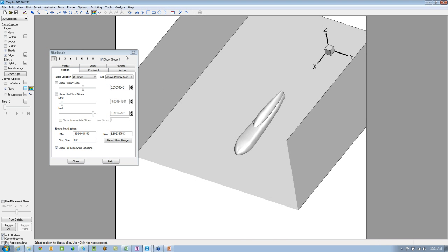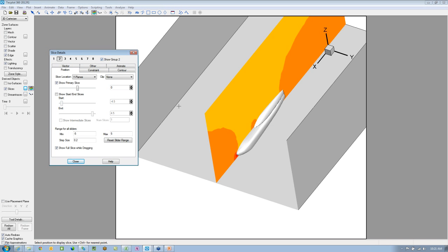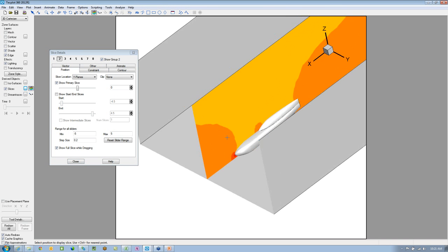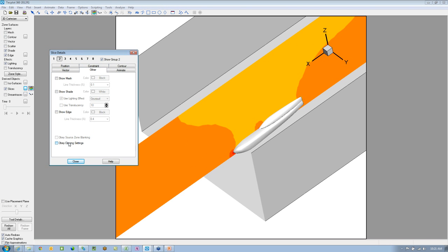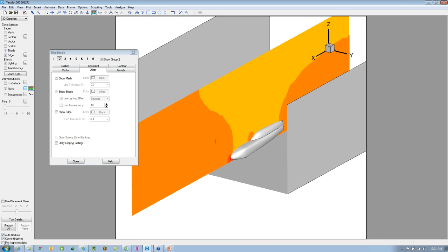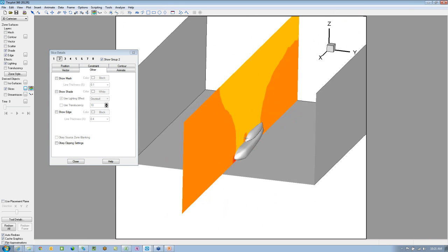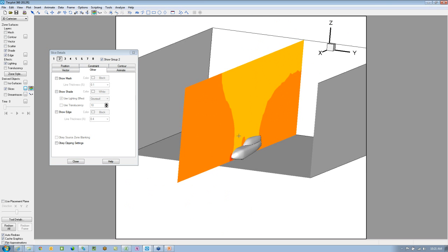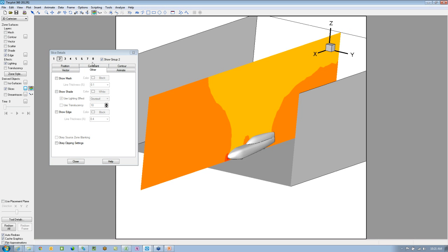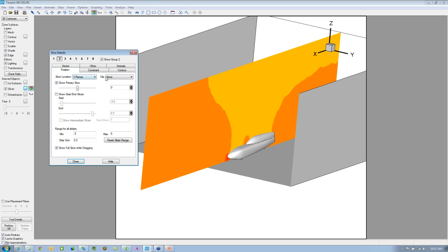Okay, and if I turn on a second slice group now, you notice that the slice group is actually following the clipping. But you do have the ability to say, well, you know, I don't want to obey clipping. I can turn that off. And in essence, you can start to clip off pieces of the geometry while still looking at slicing in other directions. And that's something we added about a release and a half ago, sorry, 2 releases ago. And a lot of people just aren't aware that that technology is available. And you can have up to 8 constraints, in this case, we're talking about clipping modes. So you can really kind of dice or slice and dice volume pretty well using that strategy.